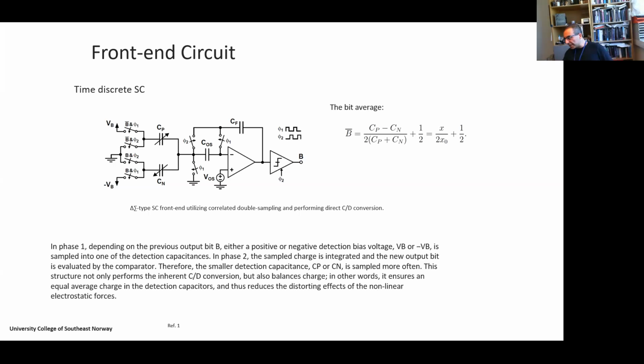Delta sigma modulators are a topic that I discuss in my class before I present this technique. So it is a kind of prerequisite for the technique I'm presenting. Basically the advantage here is that you have the output which also controls some of the input and the clocking. So feedback is almost always good, but again, the cost is that it becomes more complicated. And what kind of delta sigma we want to use, first order, second order, because delta sigma has many good properties that can be used in signal processing, which I don't want to go into.